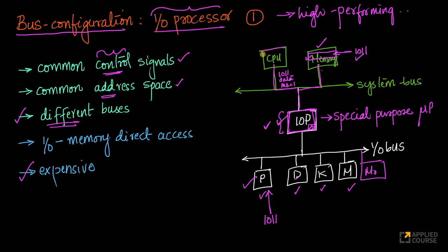Now the CPU says whether I want to read from IO or I want to read from memory. There is a special line for that, which is also connected to the memory, right? So there is a special control line in this case which says, do you want to read from memory or from the IO processor? Very simple concept here, right? If its value is, let's say, 1, it probably reads from the IO processor. If its value equals 0, it will read from memory. Now the IO processor will decide, because it's the same address, which of my devices has the address 1011? Suppose there is a special line.